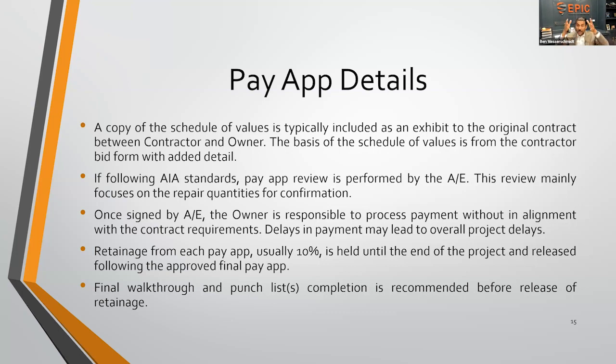If it's going to be a facade project, for example, where you're going drop by drop by drop all across the building, I would strongly recommend doing those punch lists and those closeouts per drop, because the last thing you'd want is to remove that swing stage back to that location to address some punch related item. The move of the swing stage alone is going to dwarf the level of potential repair that may be needed for a punch list item.